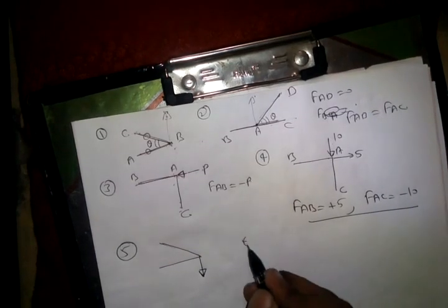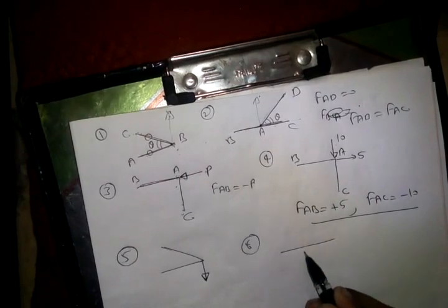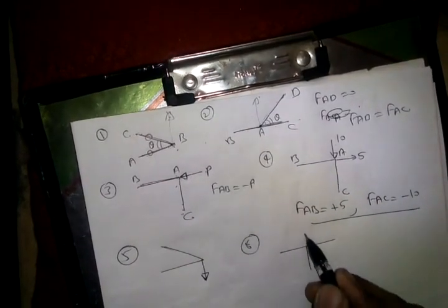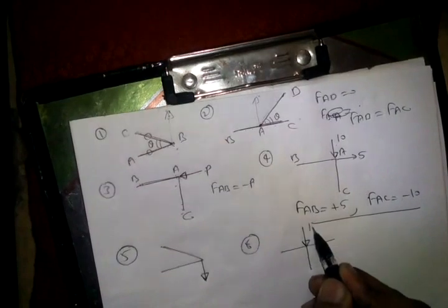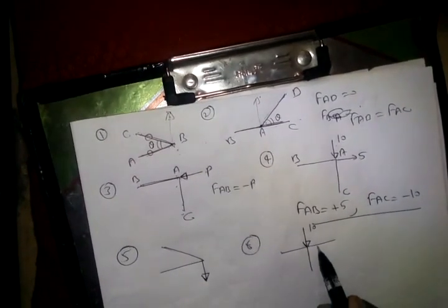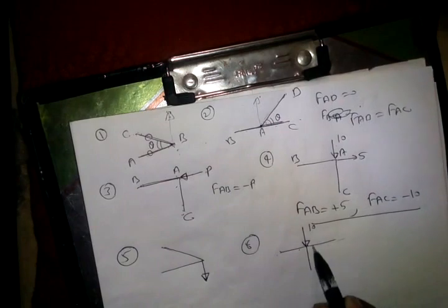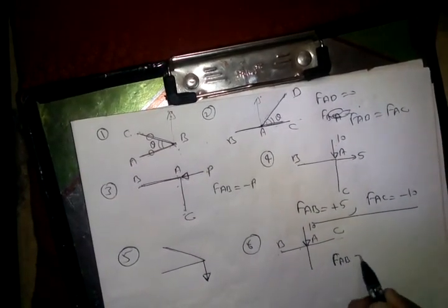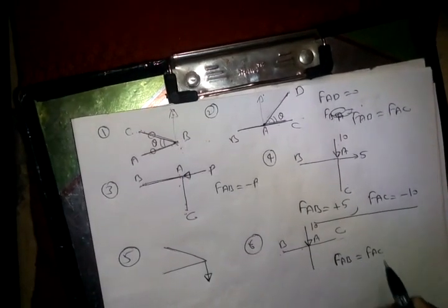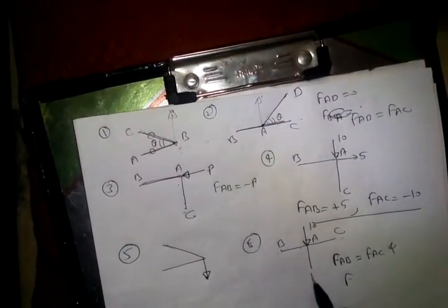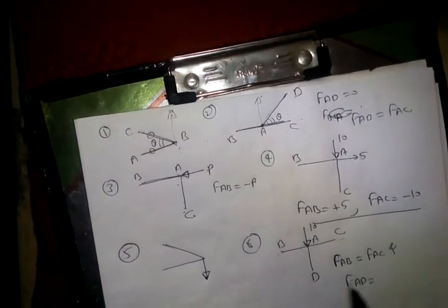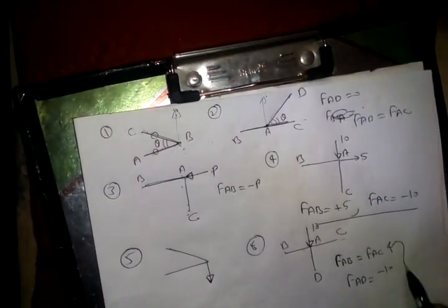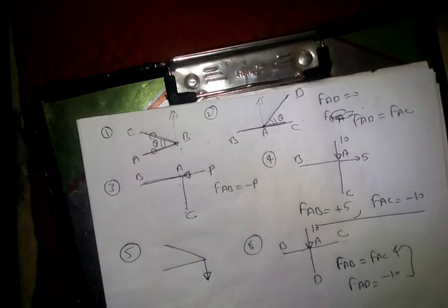Yeah, one more point is there, if this is the rectangular arrangement and loading is like this 10, in this case summation Fx 0 means this force equal to this. If this is A, this is B, this is C, means FAB equal to FAC and FAD equal to 10 compression means minus 10. This is also direct observation. Right.